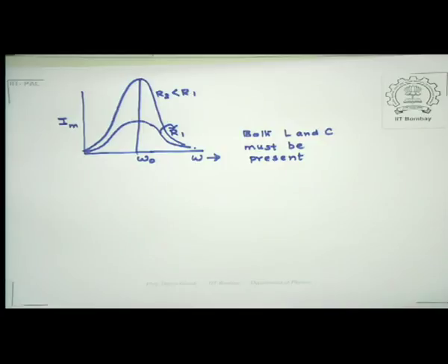And this is because, if you recall, the two reactances are aligned oppositely, and therefore there is a cancellation which is possible between the XL and XC. The cancellation becomes exact at the resonant frequency and the maximum current rises. Now this incidentally is the principle by which